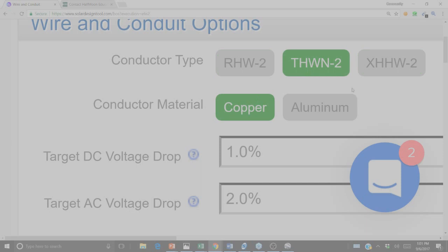And what we'll learn later is the W in these cable types refers to a wet condition. And that little -2 refers to a sunlight resistant rating. And it turns out that all of these cables are rated for an appropriate voltage to be outdoors in a wet environment in exposure to sunlight.